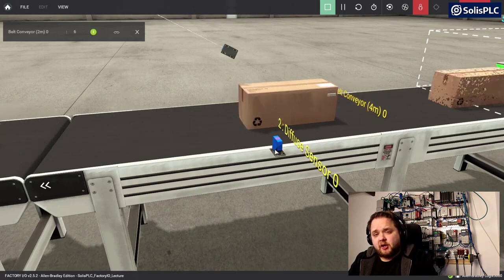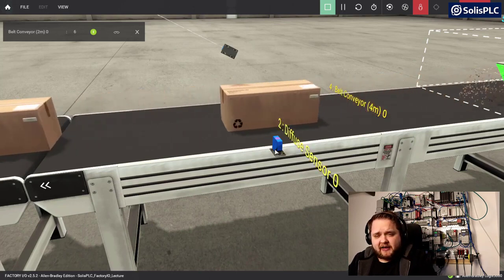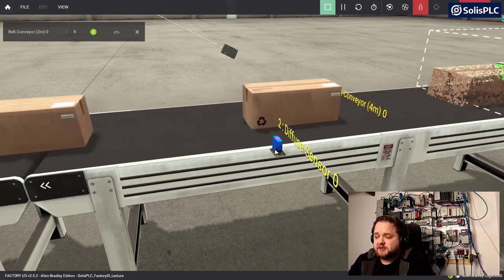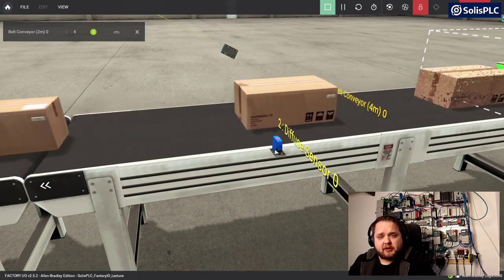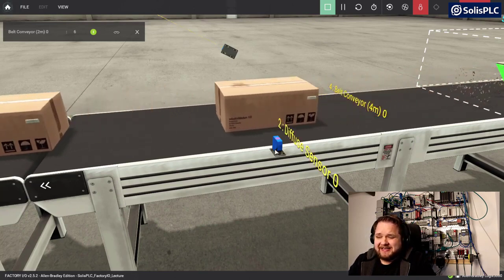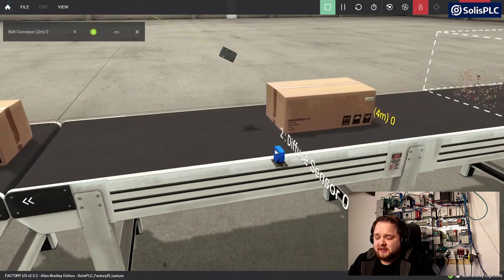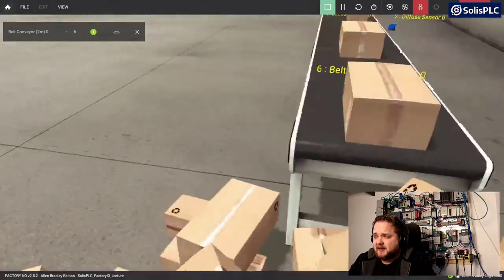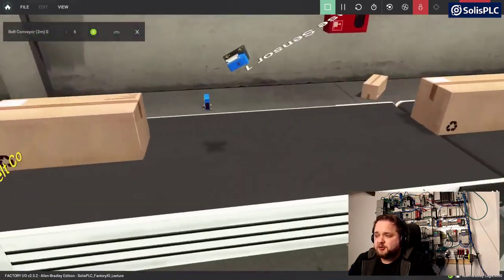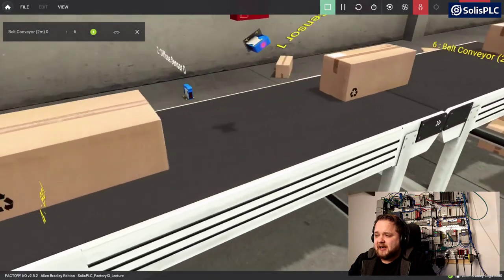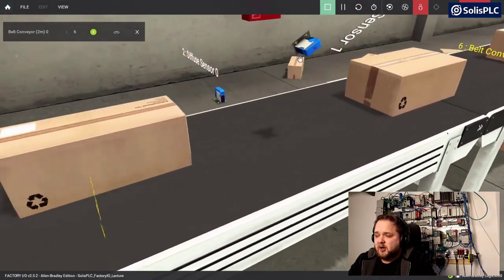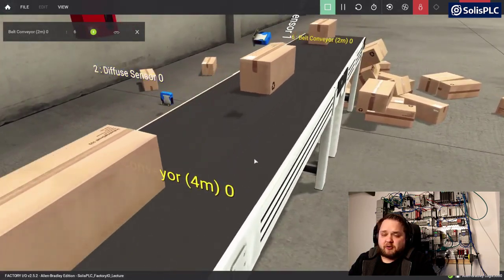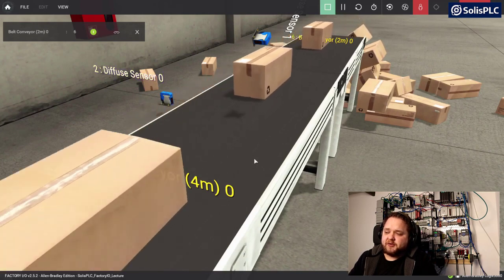Now, before we write the logic for the sensors, one thing that we need to validate, and this is a very important topic in industrial automation, as you'll see in many applications, is that the sensors don't trigger at the same time. What this creates is that when we detect a box present, we can't necessarily just read the second sensor because it will not give us the right status. What do I mean by that? Well, here you can very easily tell with the naked eye that this sensor is going to come on before sensor 0, and this creates a scenario in which you're not going to be able to easily detect in logic what the box looks like.